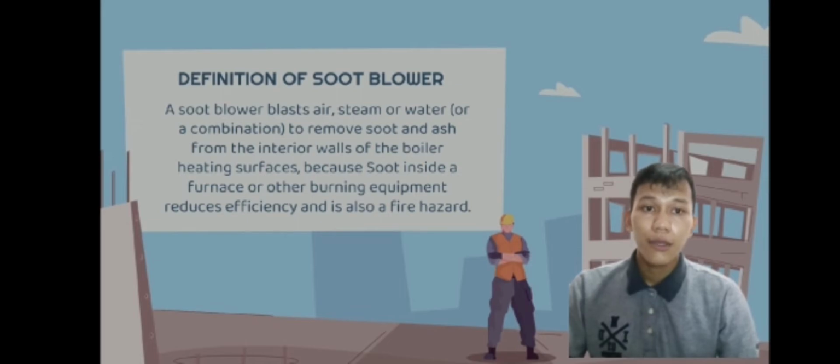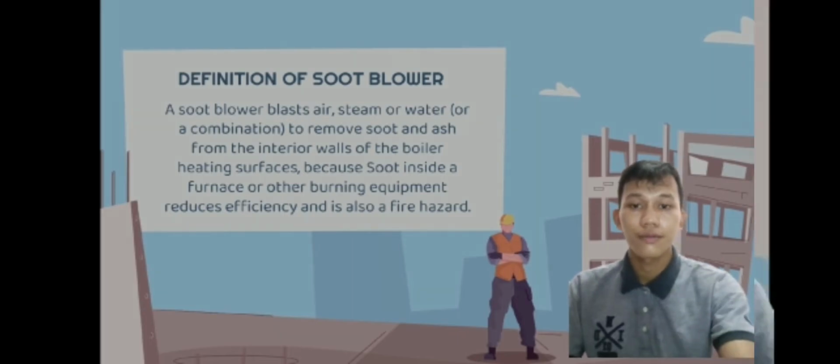Lastly, with any reciprocating and rotating equipment, effective sealing of the soot blower is important because any combustion gases and particulate escaping from the boiler can create occupational and safety hazards. This is where the utilization of an effective mechanical packing arrangement can reduce maintenance and ensure a safe operation.